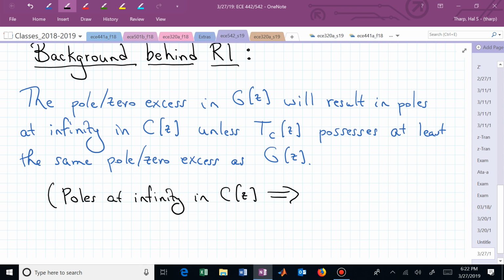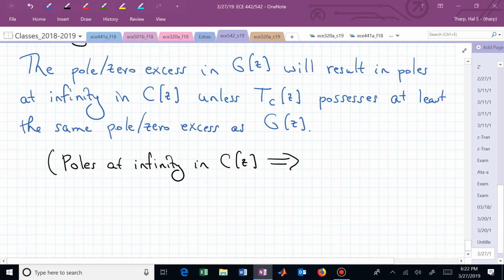Its numerator is first order, its denominator is a constant 1, it's 0th order. As we look at capital C of z equal to z, it has a pole at infinity. It goes unbounded as z gets big. Is that clear? And what does C of z equal to z correspond to in terms of behavior?